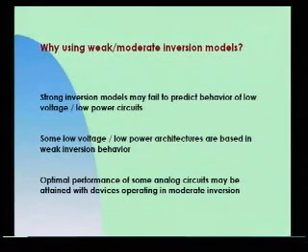Okay? There are some circuits that are designed taking advantage of the exponential behavior of the transistor in weak inversion. And so, how can you use a strong inversion model to analyze or to design such circuits? You must use a weak inversion model.